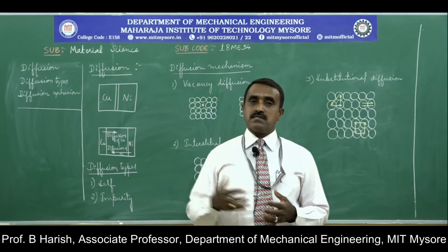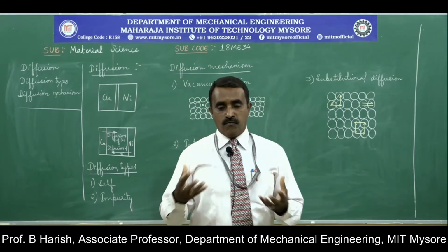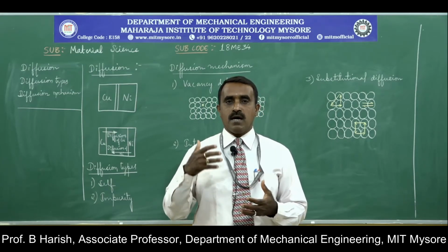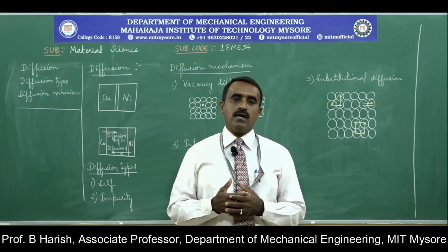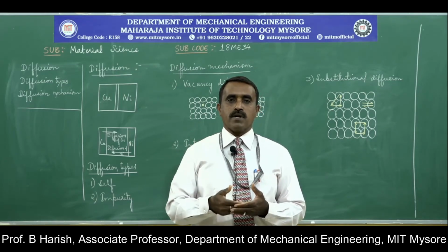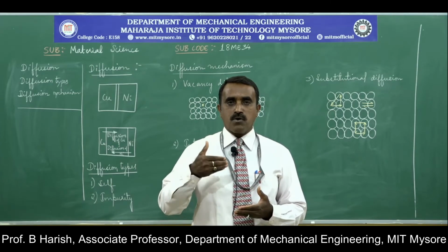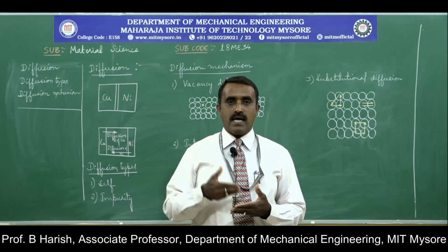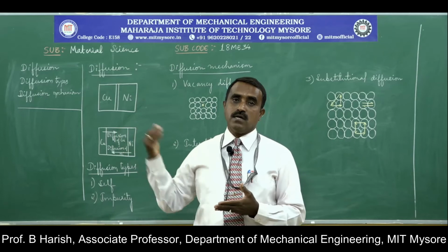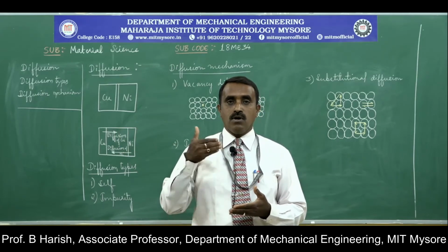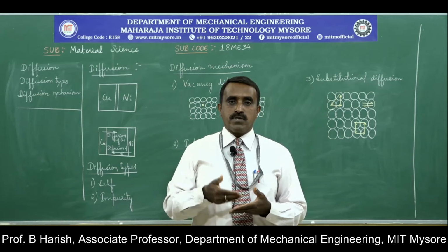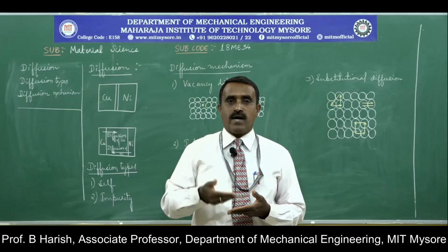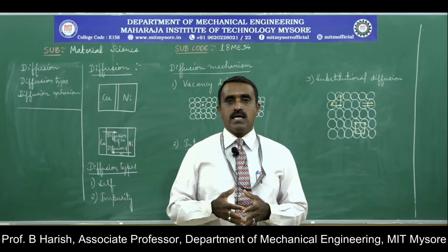Now, what is the necessity of studying diffusion? If you take an alloy, for example a copper and nickel alloy, nickel will be introduced into copper. We should know at what rate the nickel atoms get diffused into the copper atoms. That is the reason why we should know this concept of diffusion. We should know the time it takes and how this diffusion, the movement of atoms, takes place.